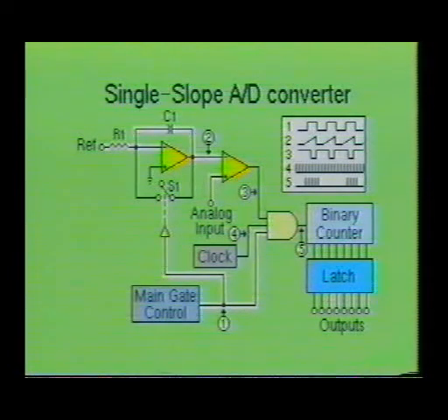There are advantages and disadvantages with the single-slope converter design. Some of the disadvantages found in the single-slope integrator AD converter are: 1. The ramp voltage may be nonlinear. 2. The clocking pulses may be unstable over the conversion process. And 3. Certain noise impulses tend to cause errors in the ramp generator output voltage. The primary advantage of this circuit is its simplicity and low cost.